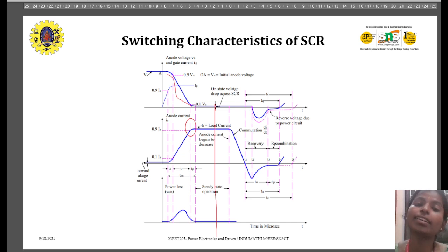It's used in low and medium frequency rectifiers, general SCRs, and inverter applications require fast SCRs. So it depends. So the switching characteristics of an SCR are turn on delay, rise time, spread time, and turn off delays. It has reverse recovery time.